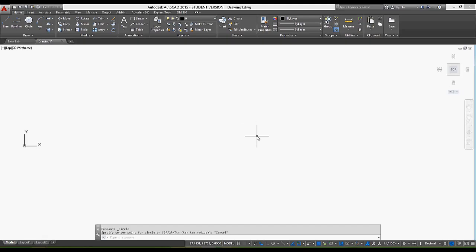Essentially, you can zoom in and out by scrolling up and scrolling down. It's hard to see now because we don't have anything in model space. But when you start to use it, you can either zoom in and out, or these are also commands too. So I can type in P for pan, hit enter, and get that same pan hand. It looks a little bit different. Now the fingers are more spread out, as if I just grabbed it from my mouse. And then again, hit escape to get out of that.